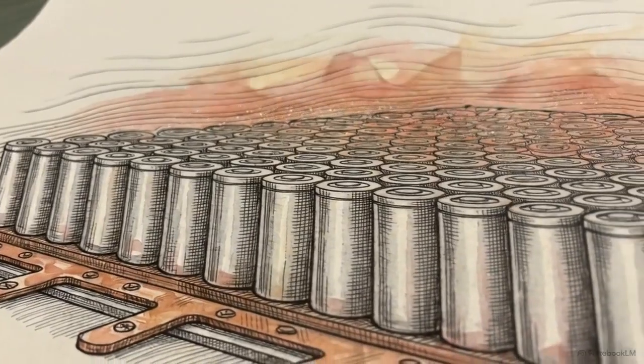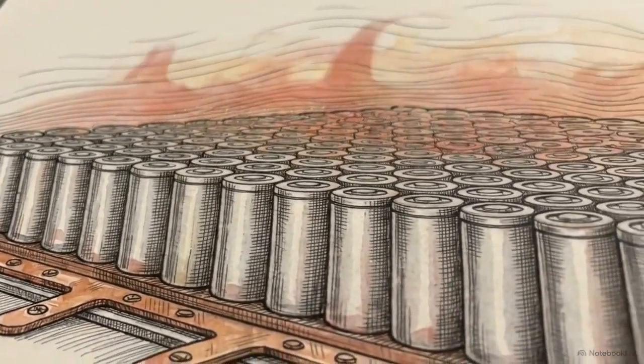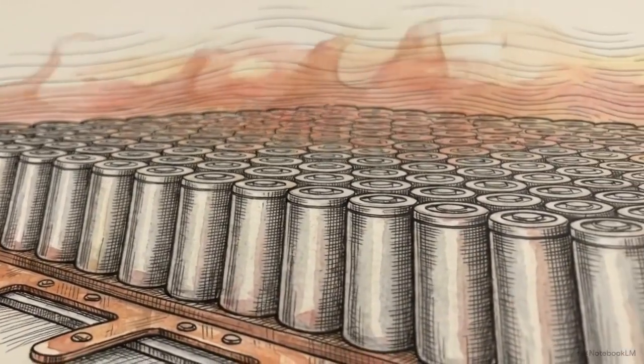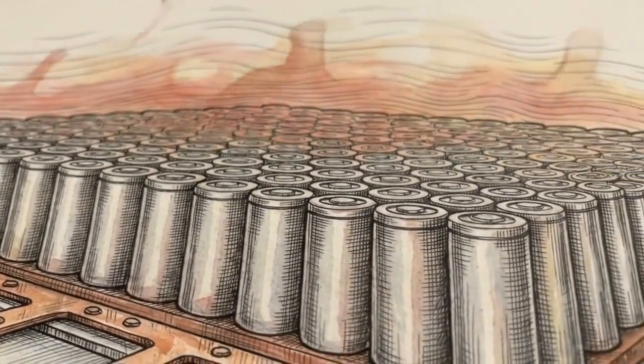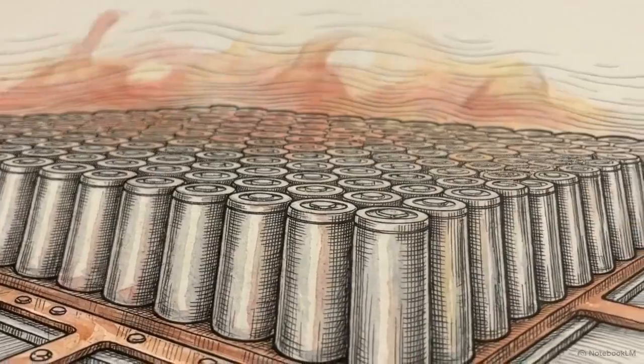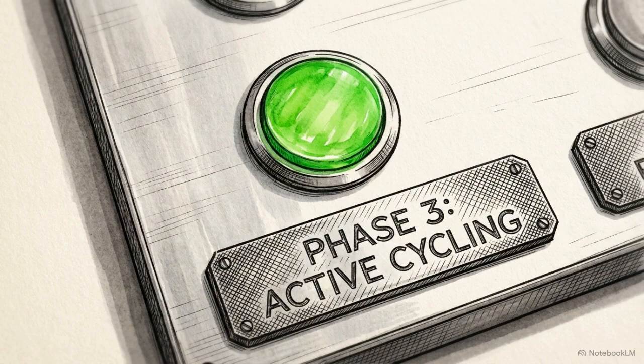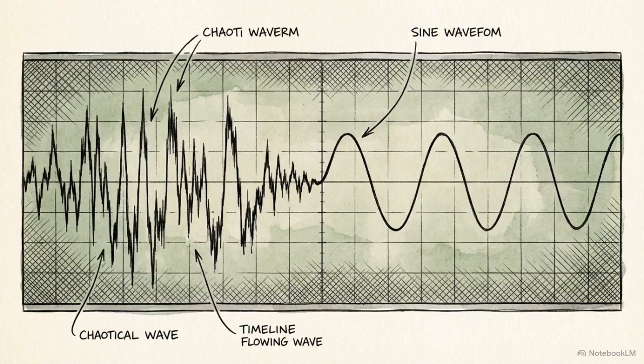Until this internal thermodynamic baseline is verified across every single cell, any subsequent electrical testing will yield contaminated and invalid data. Once thermal readiness is confirmed, the system moves into an active phase known as preconditioning. The core purpose of preconditioning is to aggressively cycle the battery. This process mathematically erases its prior charge history and stabilizes the internal electrochemistry.